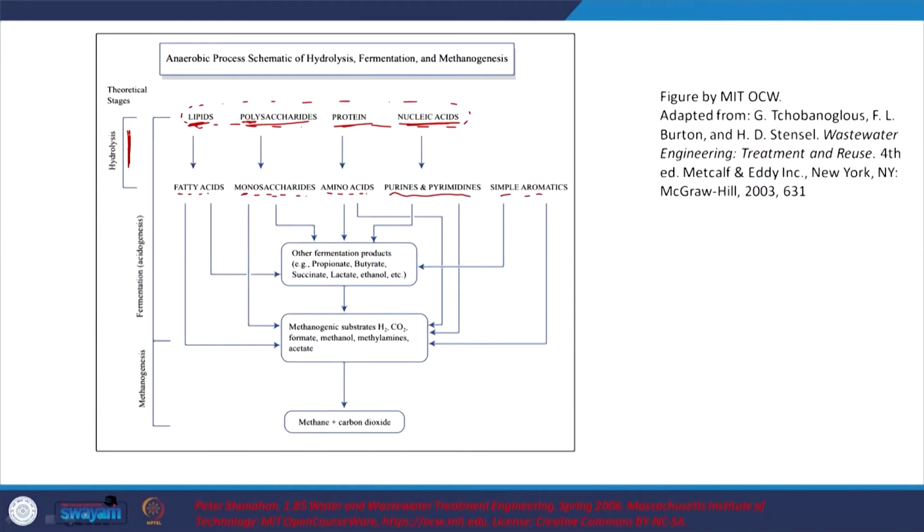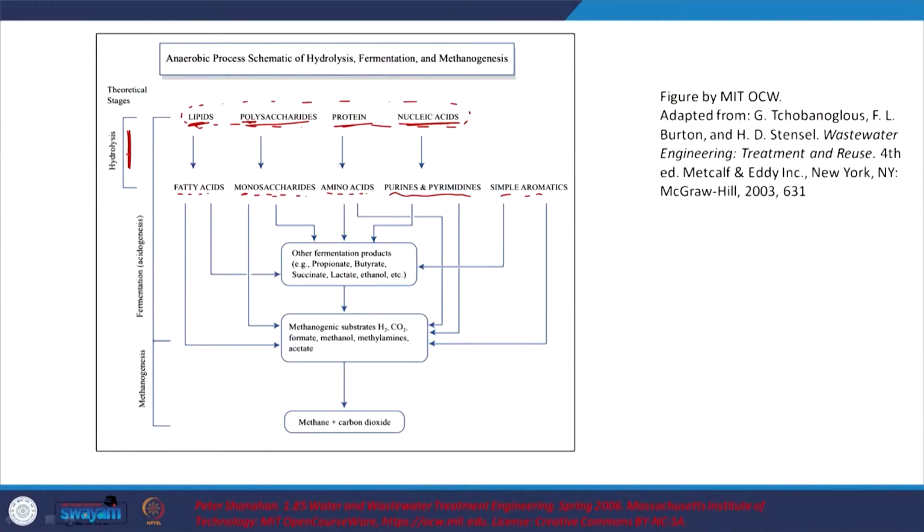I am just talking about another aspect which is relevant here, at least in the Indian context. So, that organic waste too I can let undergo anaerobic digestion and get energy from it, but their hydrolysis will be pretty slow because of the type of waste. So, typically people grind it with water or the sludge and create a slurry. So, hydrolysis is one aspect and that can be typically slow depending upon the type of compounds that you have at your inlet.